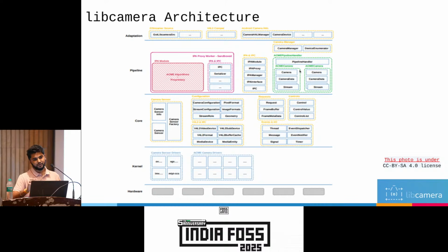Based on that you can do the configuration, and based on the hardware in the pipeline handler, Libcamera will support multiple streams also. There you can configure the maximum number of streams my hardware will handle. That you can configure too, along with the logic for loading the IPA module, meaning what type of IPA modules you want to load.